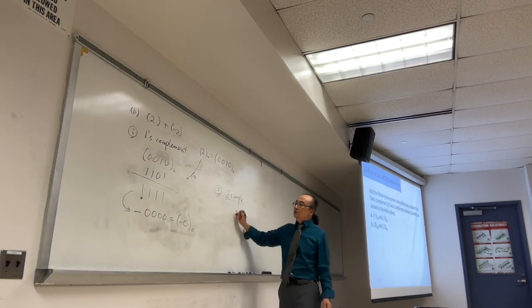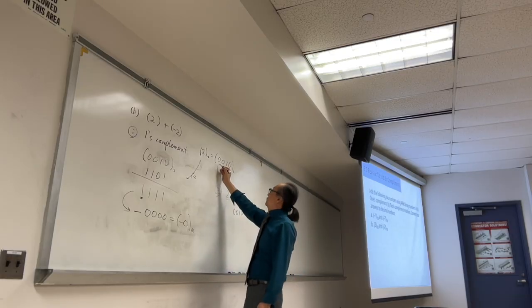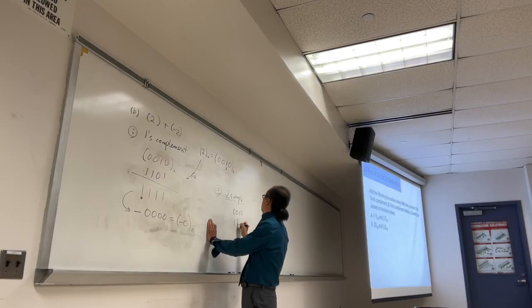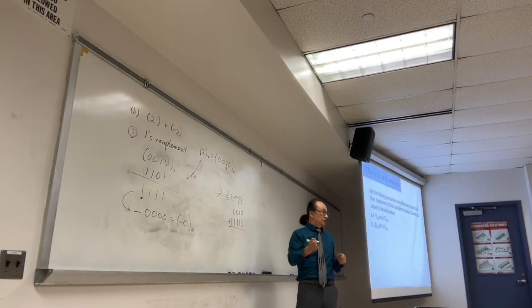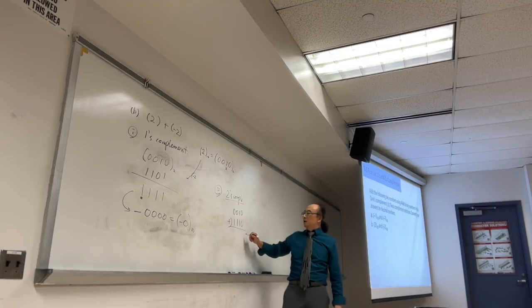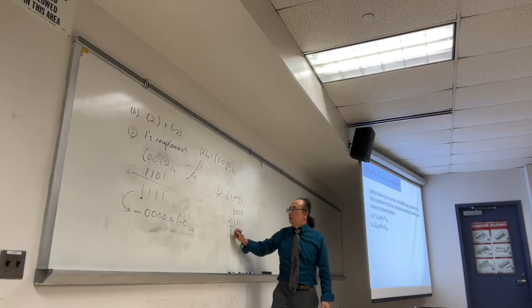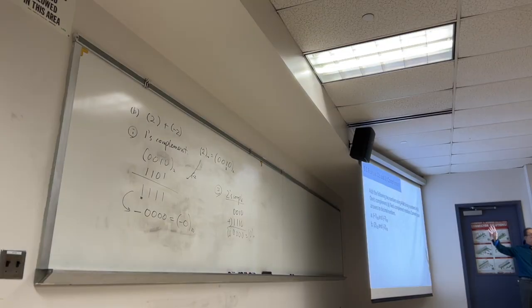If you're using 2's complement, we have 0, 0, 1, 0, and then you can read from left to the right, underline the last one, and flip the bit. 1, 1, 1, 0. So this is -2 under the 2's complement notation. And then add 0, 0, 0, 0, 1 carry. We ignore the carry, and this is 0 in decimal. When you say it's a negative number in this class in 451, we're using 2's complement only.